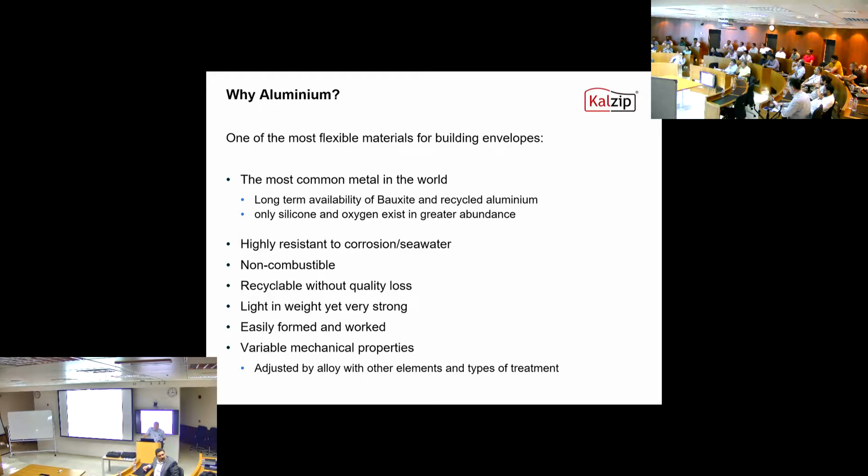You procure it locally. The rock wool will be either Fujairah rock wool or Saudi rock wool. If you look at the specification, mainly they put DCD as a must for the rock wool, and the full system should be FM approved, or something equivalent. Okay, carry on.